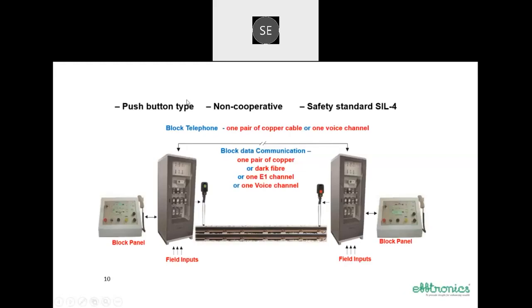Let us talk about the features of this block instrument. It is of push button type and non-cooperative, and the safety standard is safety integrity level 4. For interblock communication, a variety of mediums can be interfaced to this block instrument, like conventional copper cable or dark fiber, even a channel of OFC or a voice channel of OFC. For block telephone, one pair of copper cable or one voice channel is required.